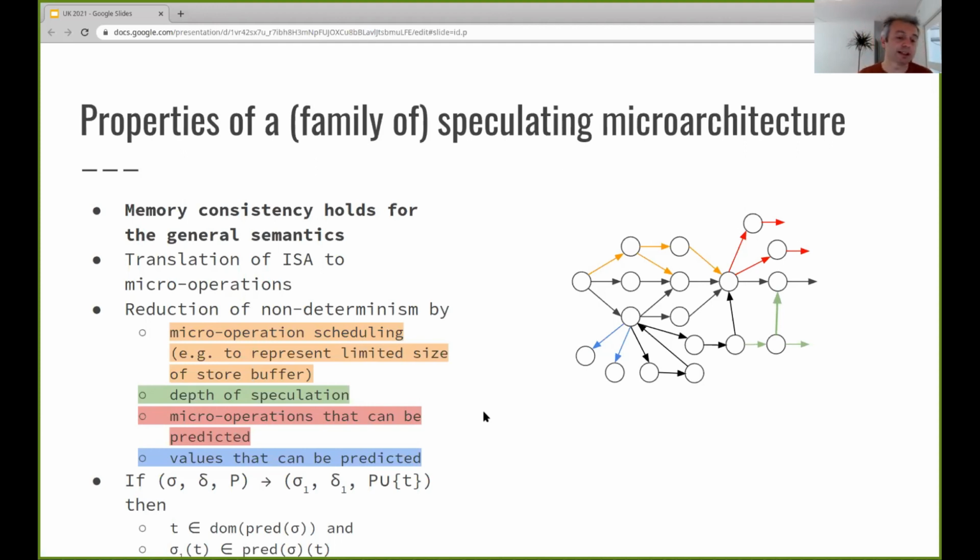Another work that we are starting to do, but still at an early stage, is modeling this work in an interactive theorem prover. Our goal is then to model an open source pipeline like the Ariane RISC-V processor, and show a refinement between this abstract model and the actual processor VHDL design, so that we can define an over-approximation of the speculation window, but also prove that this over-approximation is sound.